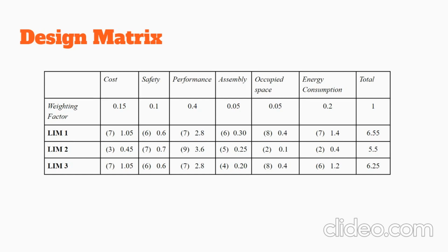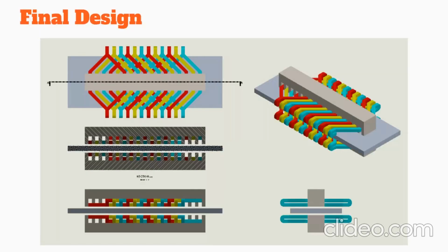After all the configurations have been investigated, an improved model that has optimal performance has been derived. Based on the research and the results, the final design was selected to be a double-sided linear induction motor with chamfered teeth. This new design will help us achieve optimal performance while significantly decreasing the end effect.